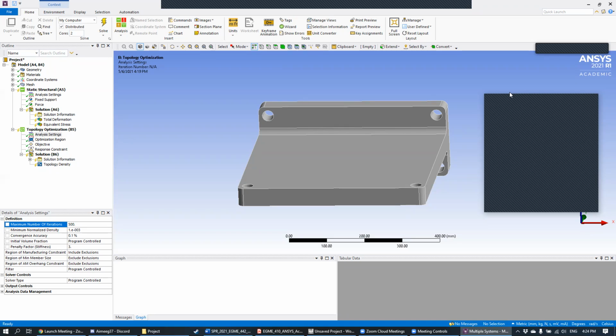The more iterations you do, the more computationally draining it's going to be, because each of those iterations is a separate finite element simulation. So you have to be a little careful about how many iterations you pick, because you can easily set this quantity to something insane, like 99999. In that case, the computer will guess and check as many times as you let it.